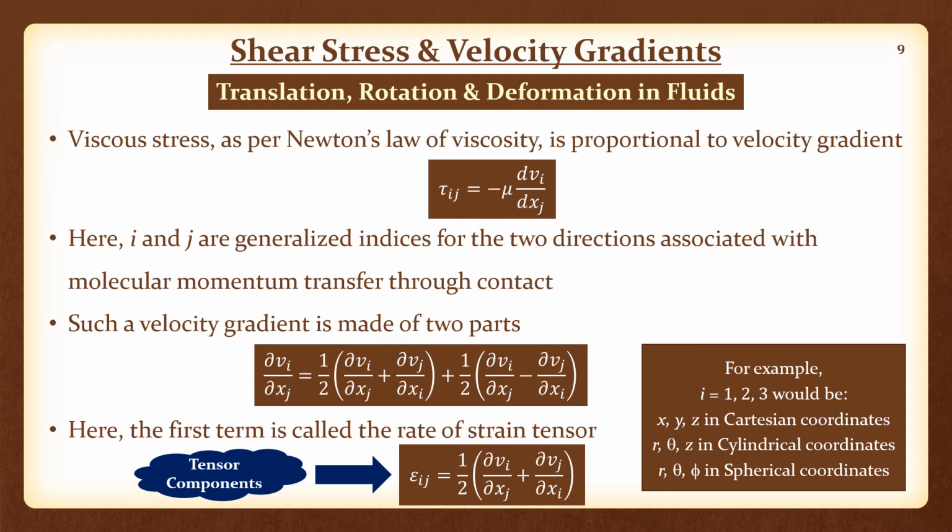You know, in this development of Newton's law of viscosity, instead of momentum gradient being taken, it is the velocity gradient that is being taken, the mass of the fluid not being captured, which is of course why your viscosity has, in its unit, kg as well, kg per meter second.